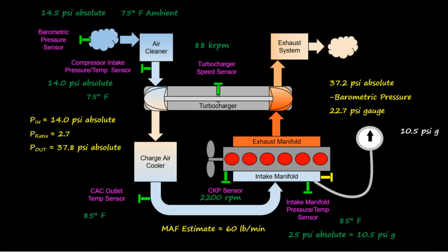So one thing I should probably mention is that many virtual sensor models are only accurate under specific engine operating conditions. Oftentimes this requires a moderate or even a heavy engine load. So ideally, the manufacturer is going to provide you that information in their service information. They'll tell you what the operating conditions are required to set each diagnostic trouble code. But I think you as technicians know that this is often not the case. So next time we'll take a look at the exhaust manifold temperature and how that is calculated.